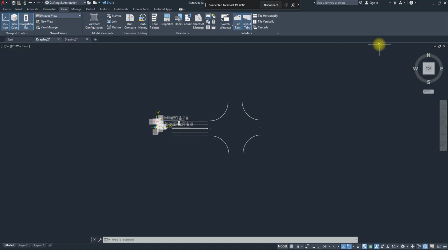I'm looking for the word we use. It's not coming. But we can find that here, still in our View tab, and it's called Design Center. So both Design Center and tool palettes do the same thing. They house libraries of tools that AutoCAD has. You understand? The difference is that tool palettes just bring a few of the things from the library for us to easily bring them. But for Design Center, you will have them categorized. So you can go into the different categories and start bringing them out.